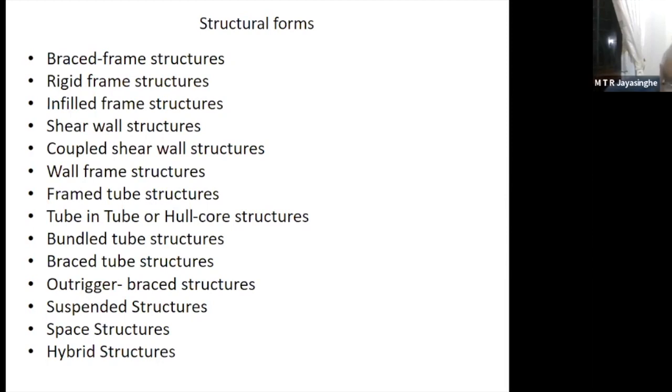So because of that reason, most of our peat layers can be limited to about 6 meters. Very few places like Orugodawatta, you get 10 to 12 meters of peat. So basically, you don't have to worry too much. If you have peat soils, make sure you anchor it at the bottom, anchor it at the top with a beam system. The moment you do that, rotations will become minimum. The piles will bend in double curvature bending. Because of that reason, you need full length reinforcement.